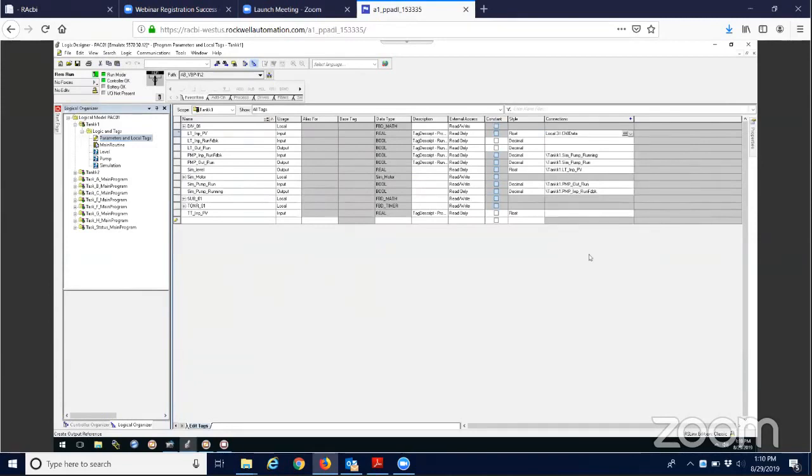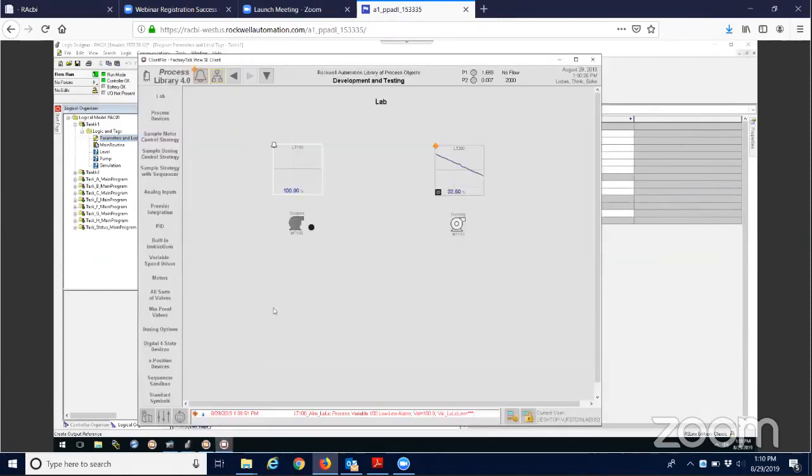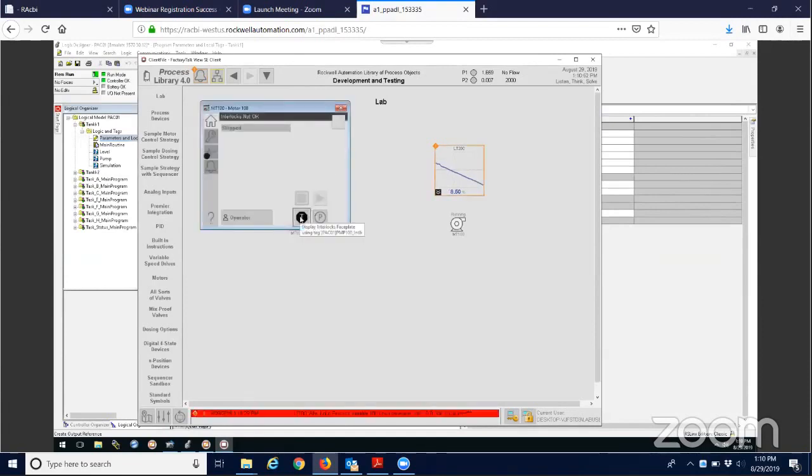Okay. All right. So now that variable is looking at my analog input card. And actually you just saw it go from 100 to 0 right there. So I go back to my HMI and now I'm at 0. Well, my logic just told me that I had an interlock that was going to reset me back to 100, and you just saw me cycle. Well, now why am I at 0? And if I open up this interlock, I can't reset my interlock either. That's because I'm looking for that real world IO and it's out of range.